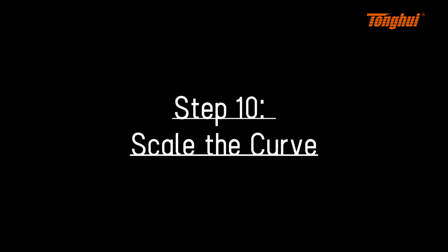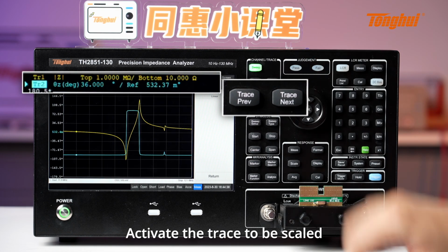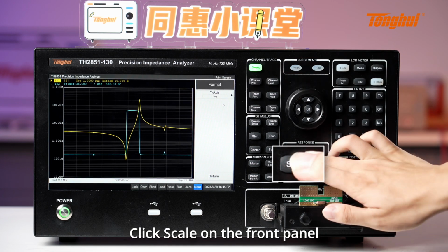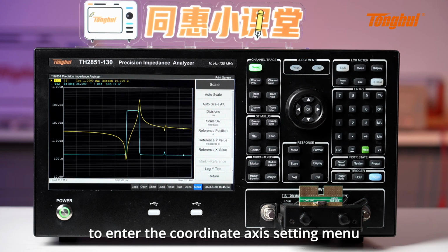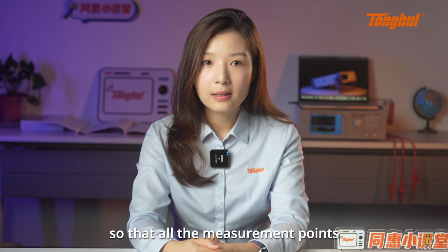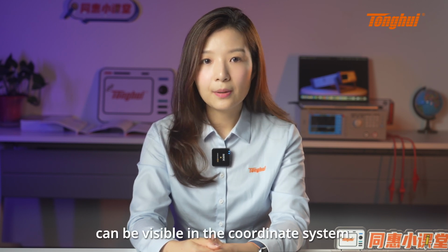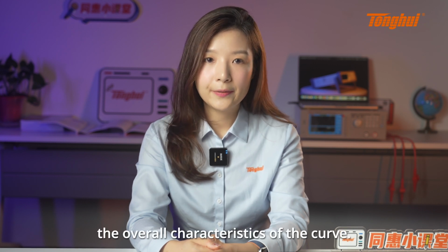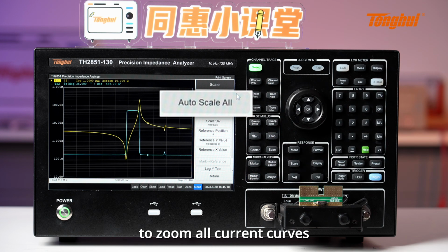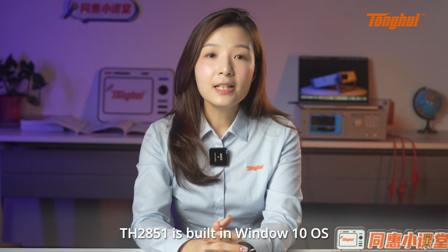Step 10. Scale the curve. Activate the trace to be scaled through Trace Previous and Trace Next. Click Scale on the front panel to enter the Coordinate Axis Setting menu. Click Auto Scale to zoom the active curve so that all the measurement points of the active curve can be visible in the coordinate system. Then you can observe the overall characteristic of the curve. Click Auto Zoom to zoom all current curves. It is also possible to manually scale the settings.